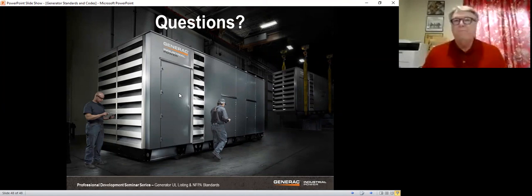Yeah, so this could be a long answer, as you might guess, but I think it's a great question. The first thing I think is all generator specifications should say that the generator needs to be UL rated. A lot of times optional generators don't really have specifications. People will just look for a generator they like and bring it in.